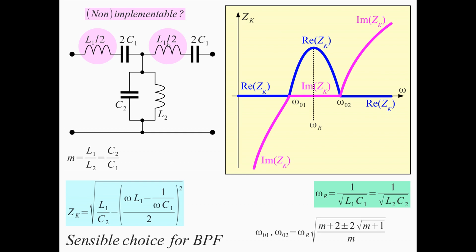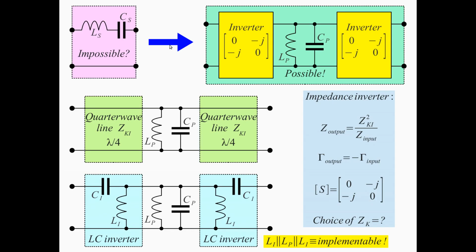So what we are going to do next is try to find a solution for this serial inductor. We are going to try to replace this tuned circuit with L serial and C serial. This is impossible because it turns out to be too large, and large inductors have their own parasitics, capacitance between the windings, and their own resonances. We may make an inductor of large enough inductance, but it will have many parasitics that will limit its application. So it is actually impossible to make this inductor.